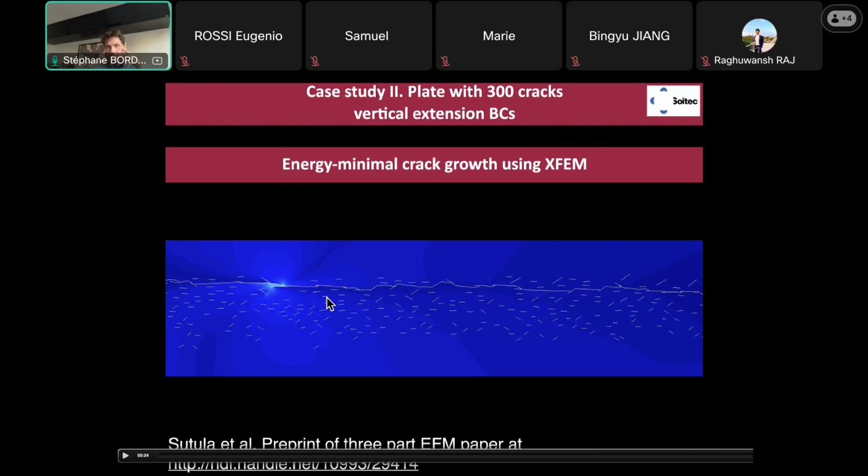So what they do is they send high energy hydrogen ions, or protons, so that they get stuck in the lattice and create small weaknesses in the material. These small weaknesses will then lead to cracks forming. They do some sort of thermal treatment of the silicon wafer. By increasing the temperature, decreasing it, increasing, decreasing, they create a reassociation of these protons, which are H+ ions, into H2 gas inside these little cracks.